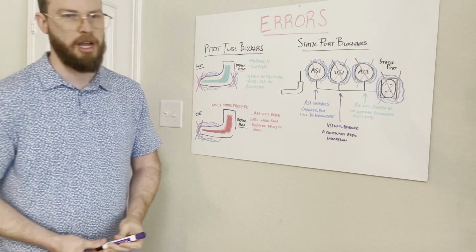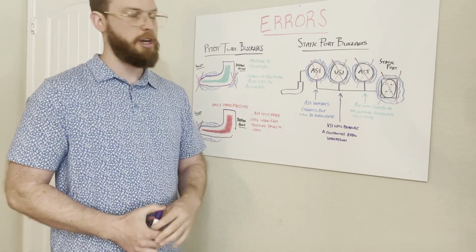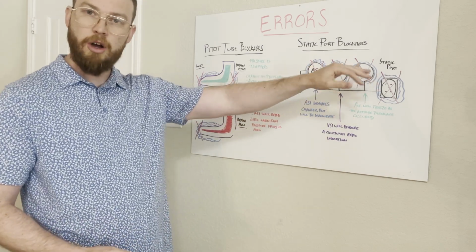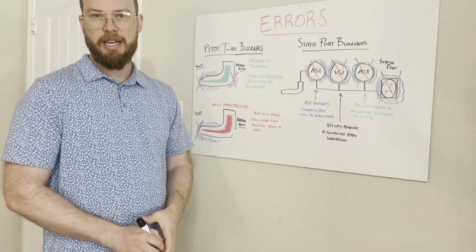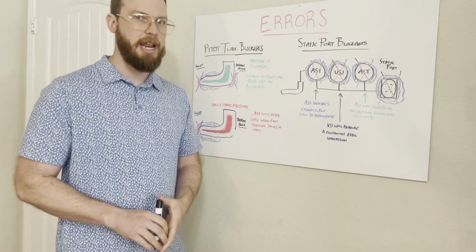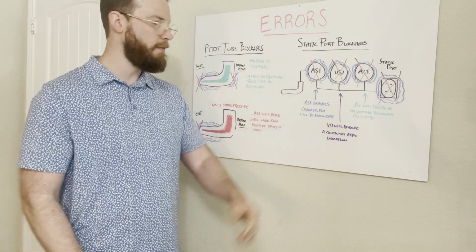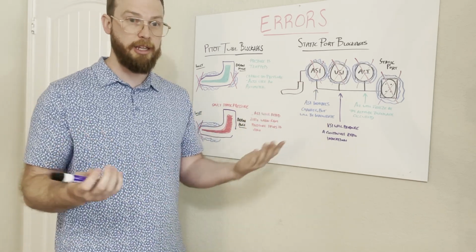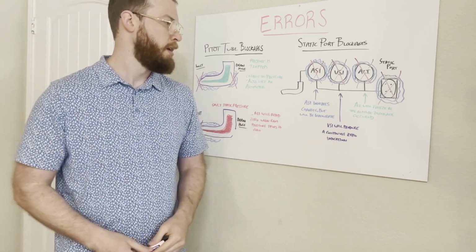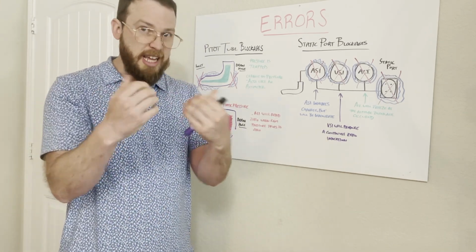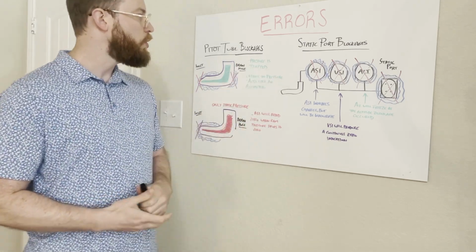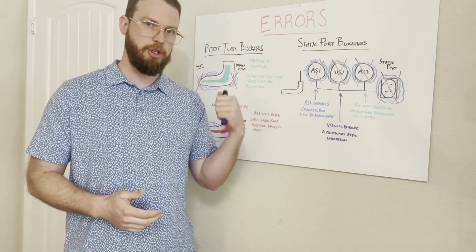Now let's go over to static port blockages. So if our airspeed indicator, vertical speed indicator, and altimeter are all blocked because our static port is frozen over or clogged, something like that, airspeed indicator is going to get some readings because we still have the pitot tube, but the readings might be slightly inaccurate, so we need to watch out for that. A vertical speed indicator is going to produce a continuous 0 indication, not going to let us know if we're climbing or descending, it's just going to stay at 0. And then our altimeter is going to freeze or just stay stuck at the altitude at which it was frozen over at. So there's a quick summary of our errors on the pitot tube and the static port.